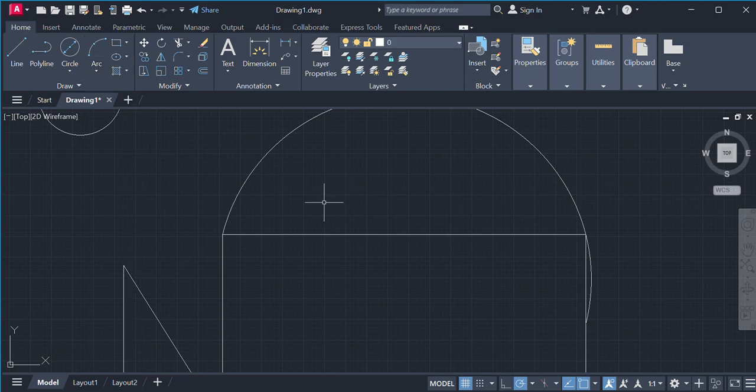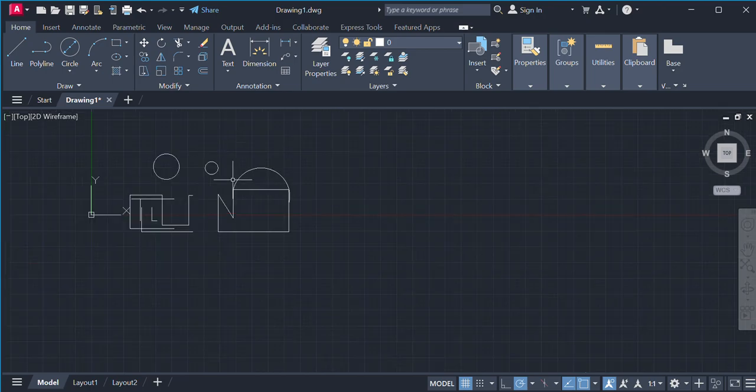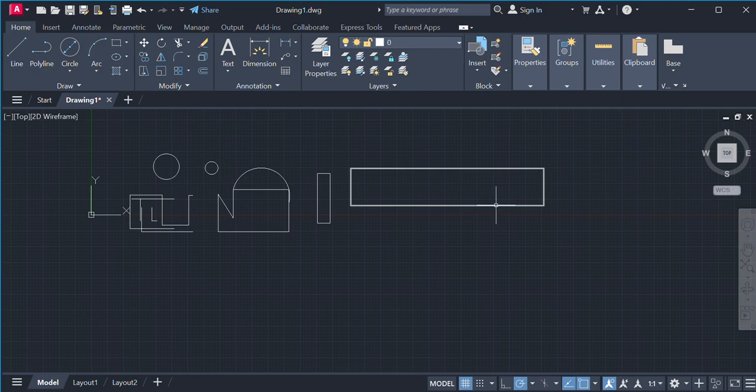I just did a demo one to show you how you would go about it. Then next up we have our rectangle command. Click on it, specify the first point, stretch it out, or specify on there that you want it to be 1,000 in length, and obviously it will follow your prompts. If you want it to be 15,000 in length, then it follows your prompt. Okay, this essentially helps you to carry out your rectangle.